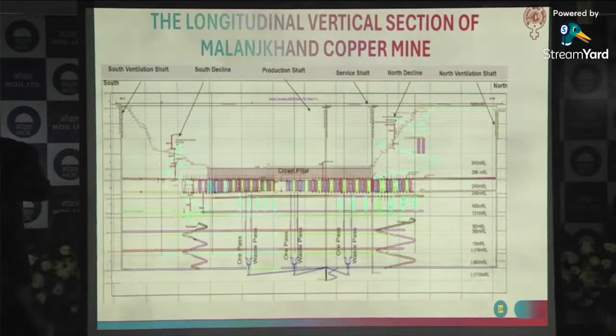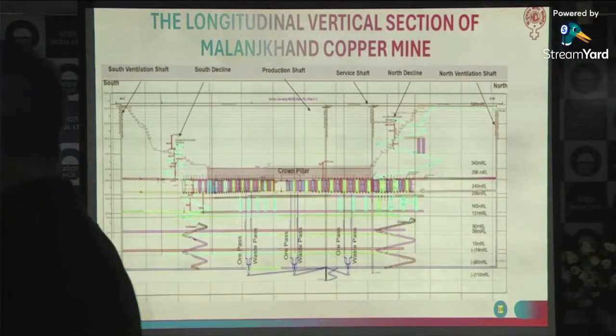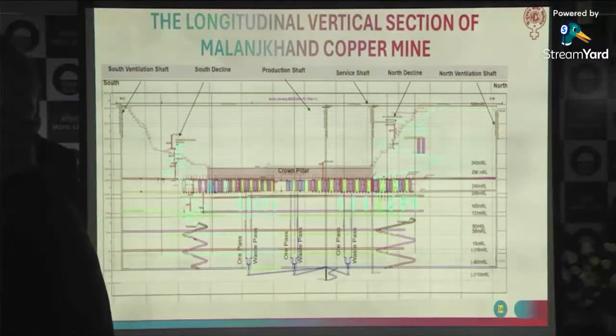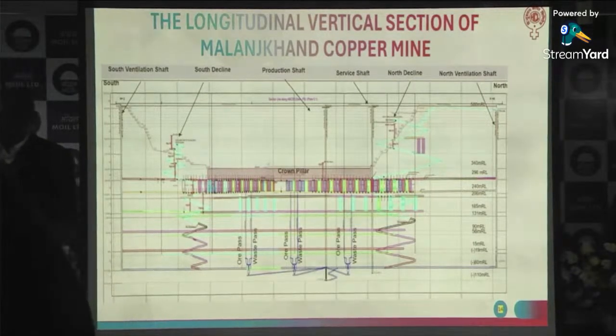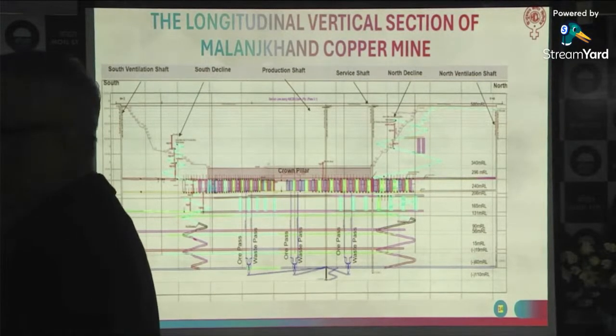The minus 20 microns is supplied by OPC. That is the only thing. The coarser particles come from GGBS. That is why they are using 9%. Actually, it's a binder only, just to reduce the fineness of the tailings.